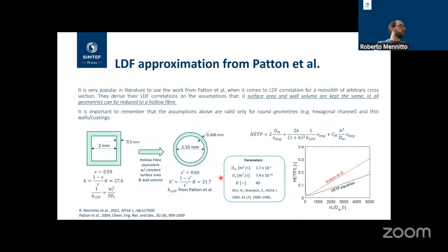Before we go to non-isothermal conditions, I just want to draw attention to something that is very often cited for the linear driving force correlation. When we write numerical models, we often use the linear driving force approximation for the diffusion in the solid, and it makes sense. There is a nice paper from 2004 from Patton and co-workers where they tried to derive the linear driving force for any arbitrary channel of a monolith.